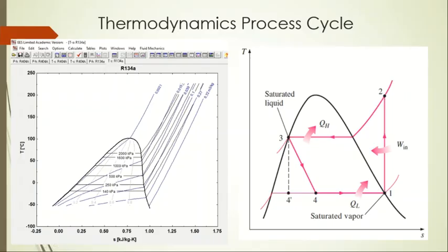So here the temperature is quite high, and you can also see it moves up to 60 degrees centigrade at this part when we run this unit. After that, the discharge of the compressor will enter the condenser, where it comes in contact with the atmospheric air, which in hot summer conditions is around 35 to 40 degrees centigrade.